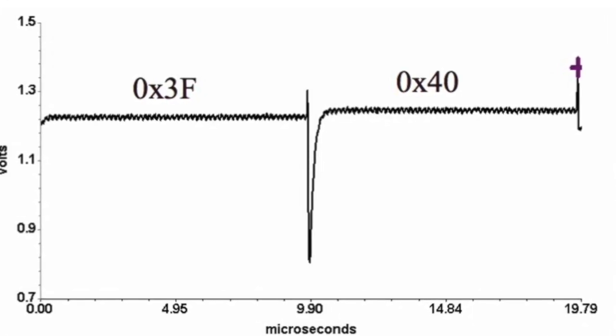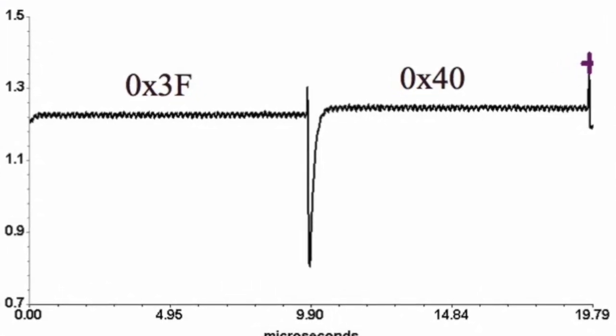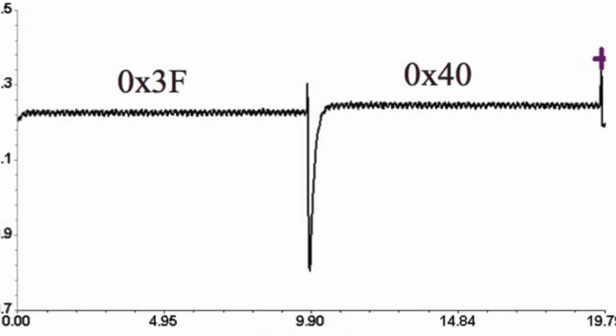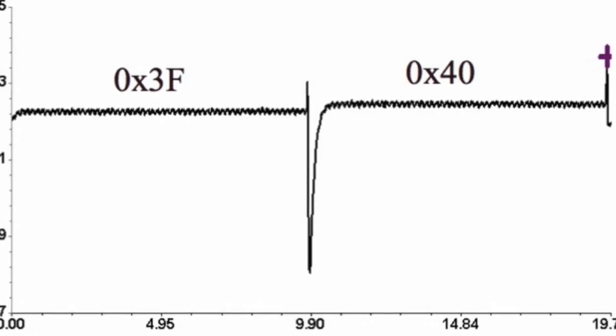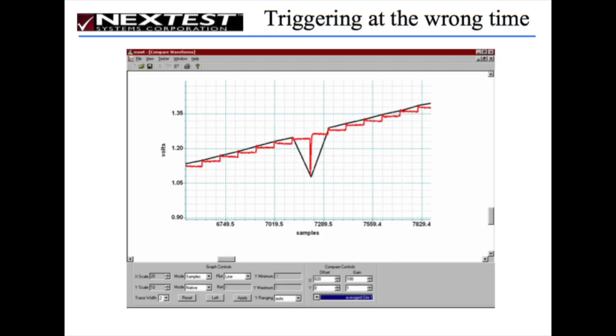We found on a Philips microcontroller, we had a big glitch. And this is the real glitch. We found we had a big glitch in the waveform coming out of the DAC, because it's a microcontroller that has a DAC and ADC. The DAC would generate a big glitch when we went from 3F to 4.0, because there was some problems with the way the logic is done.